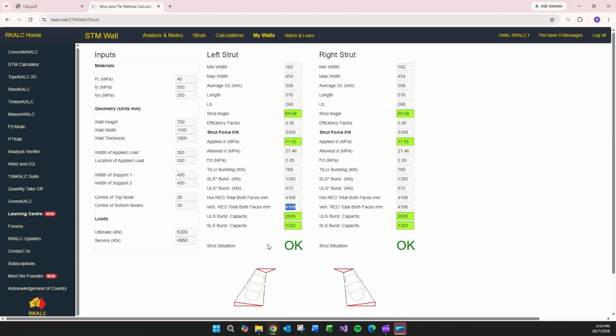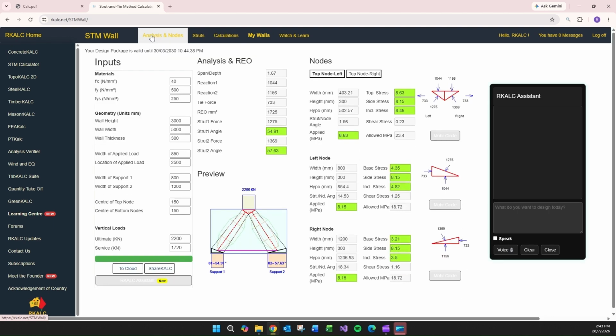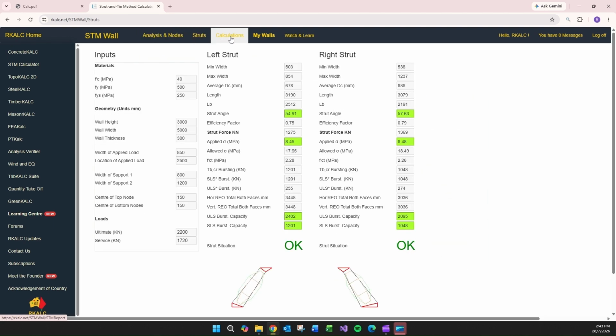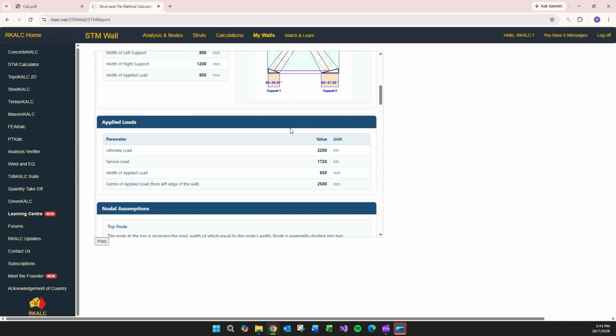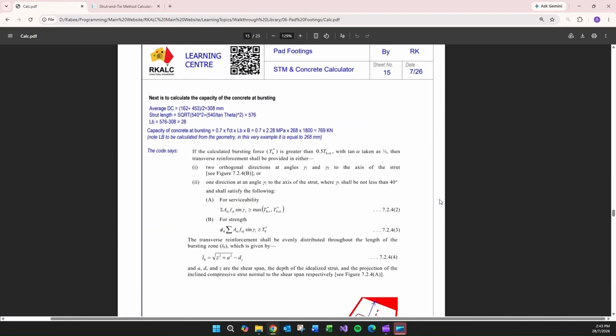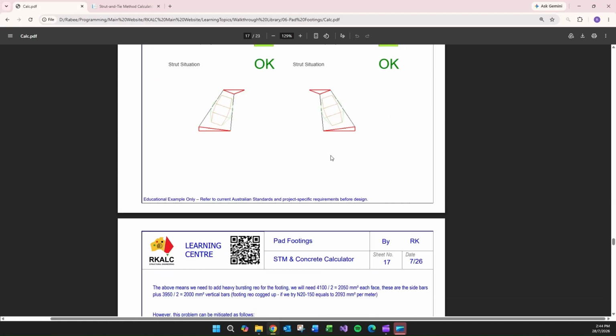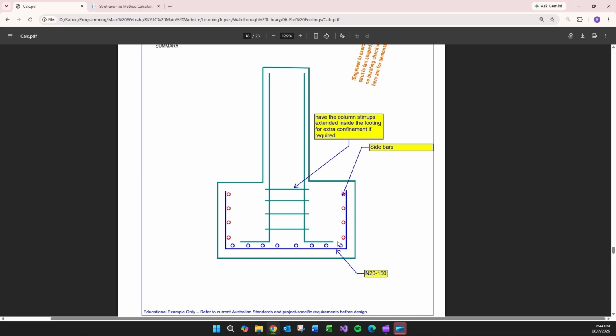Look at the first example we've published on the Learning Center to learn about how you put the reinforcement into the struts. And once you're done, you just click on calculation. So you'll get the same stuff. I need to, first of all, activate all of that and then click on the calculation. So you'll get the calculation report for the whole thing. That is the one that you see at the end of this report. That is all about it, I would say. At the end of the day, the reinforcement will be looking like this.